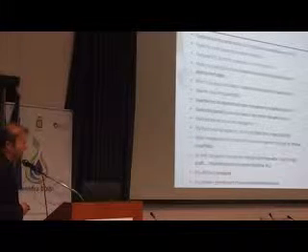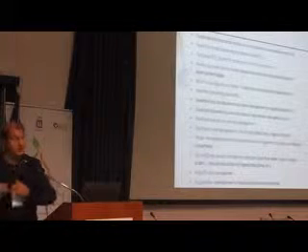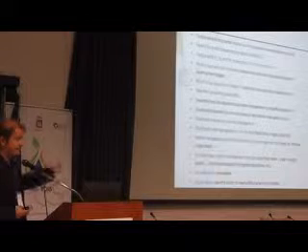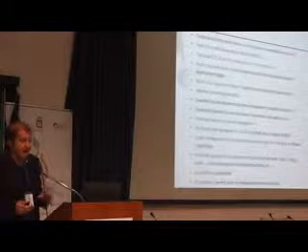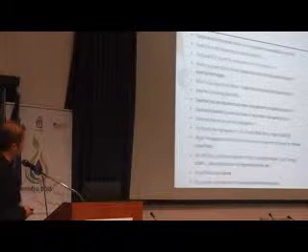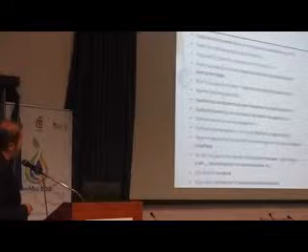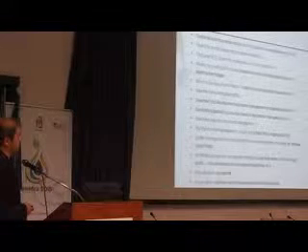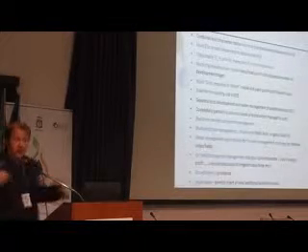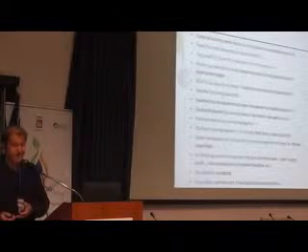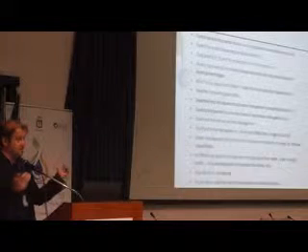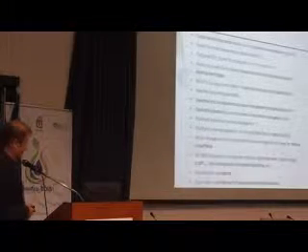We know that in the past we simulated everything using a day-by-day approach. But nowadays we apply also heat units as the way to estimate the development of the crops. We apply also a multi-crop response to water approach. So we did not apply only the Stewart equation, but we applied also the Rao equation, in which we use different sensitivity of crop during different growing stages, and a multiplicative approach to get yield losses.